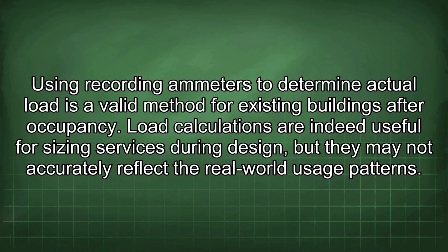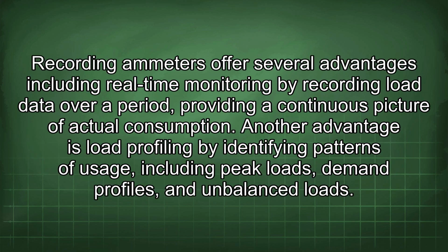Using recording ammeters to determine actual load is a valid method for existing buildings after occupancy. Load calculations are indeed useful for sizing services during design, but they may not accurately reflect the real-world usage patterns. Recording ammeters offer several advantages, including real-time monitoring by recording load data over a period, providing a continuous picture of